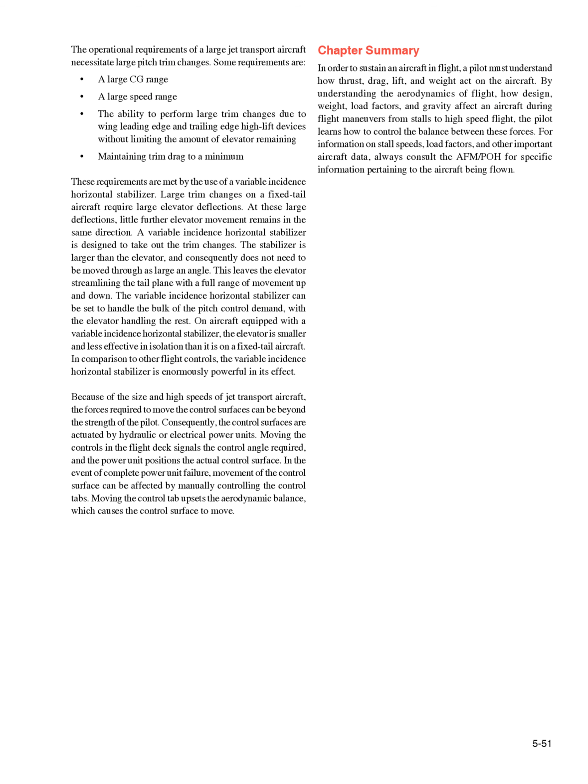The operational requirements of a large jet transport aircraft necessitate large pitch trim changes. Some requirements are a large CG range, a large speed range, the ability to perform large trim changes due to wing leading edge and trailing edge high lift devices without limiting the amount of elevator remaining, maintaining trim drag to a minimum. These requirements are met by the use of a variable incidence horizontal stabilizer.